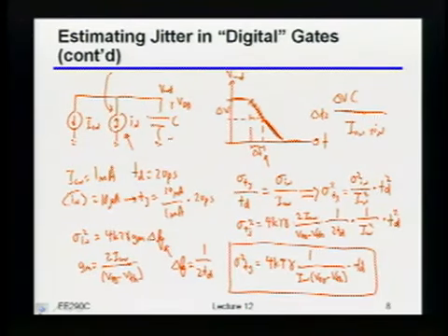That's not necessarily the end of the world, because at that point you're using the inverter like an amplifier, right? A lot like a low noise amplifier design, you'd be trying to design the inverter to be a low noise amplifier. But you are indeed correct that in general, if you want a low jitter system, you want as sharp an edge as you can, or at least as reasonably sharp an edge as you can, throughout that entire chain. That's absolutely true.